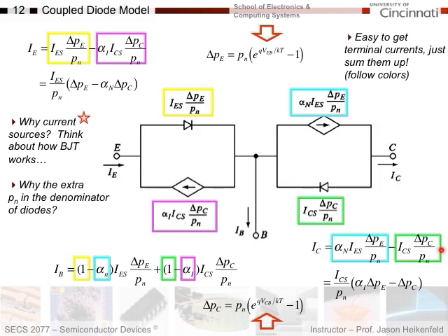Okay? Now, going one step further, remember that in normal mode, looking back at the emitter, the emitter acts like a forward bias diode. And in inverted mode, the emitter acts like a collector, right? So in inverted mode, the emitter acts like a collector. Same thing here on the collector. Here's my normal mode. It's acting like a collector. Wow, that makes sense.